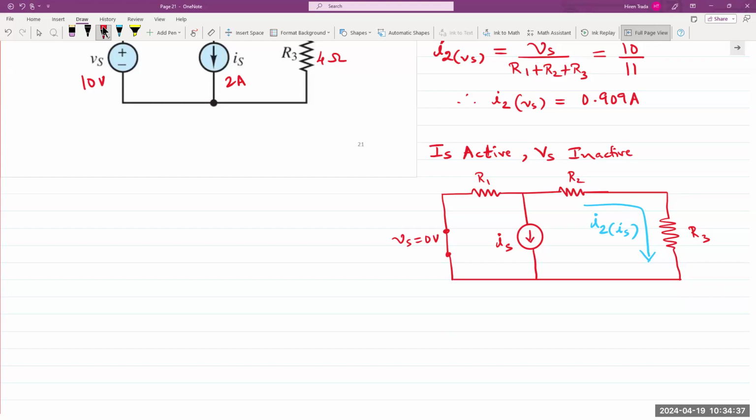But in theoretical modeling, especially for audio applications like audio amplifiers, it's very, very useful to model them as constant current sources. Meaning the current level remains the same. The voltage will change depending on what the load is or the circuit is. In a constant voltage mode, the voltage remains the same. Meaning if it's a 10-volt source, it will output 10 volts. Doesn't matter what circuit resistances you connect. The current will change, but the voltage remains the same. That would be voltage source and current source. Does that answer your question?